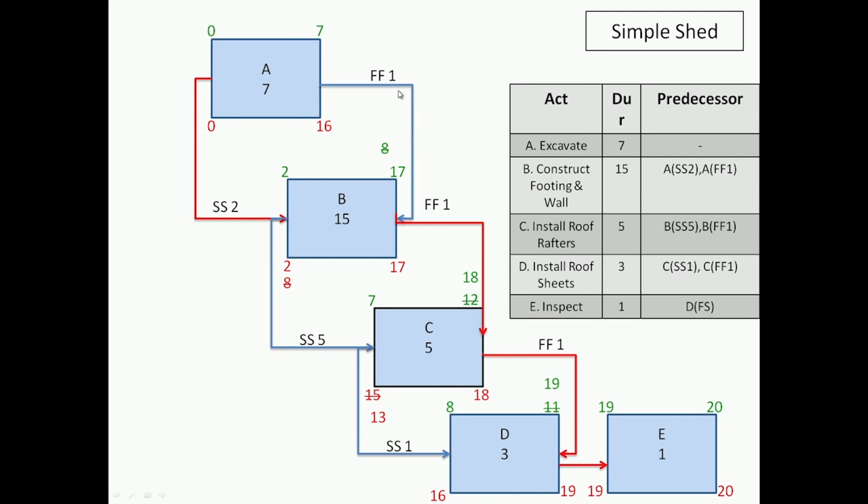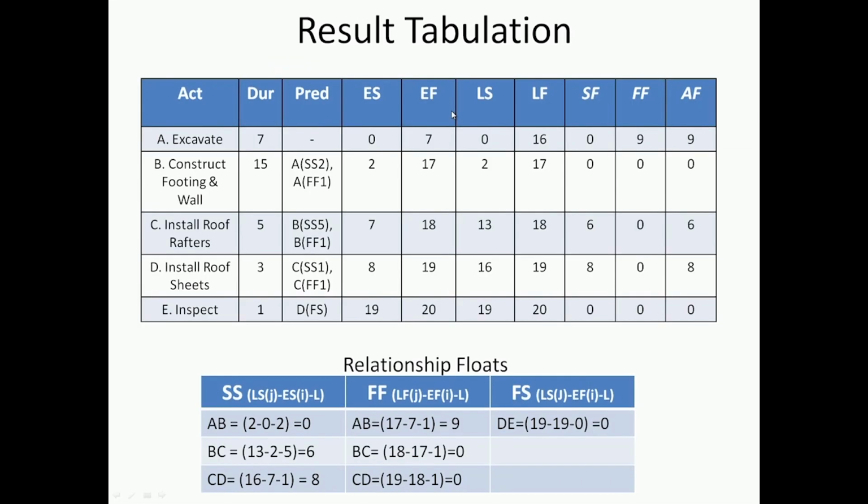So, just as we had total float in the AON and it is shared along a chain of activities, these floats here are also shared based on how they are along the activities, okay. So, you have to be careful that it is not like a free float, it does not belong only to that part of the activity. It is again shared along the path.